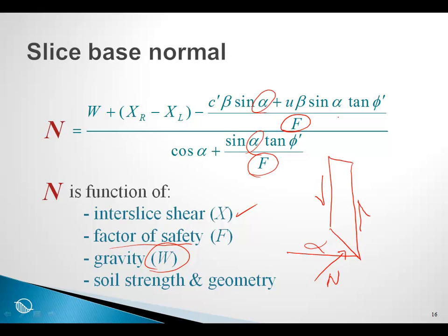How can this be? How can a stress condition in the field be a function of the factor of safety? This is one of the peculiarities of the limit equilibrium formulation, and it does have a profound effect on the normal that we compute, and consequently it has an effect on the normal stress distribution that is computed along the trial slip surface.